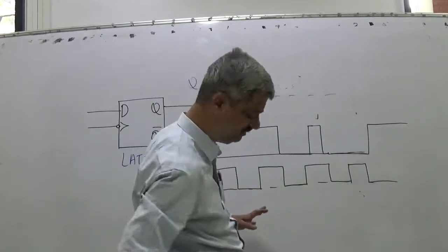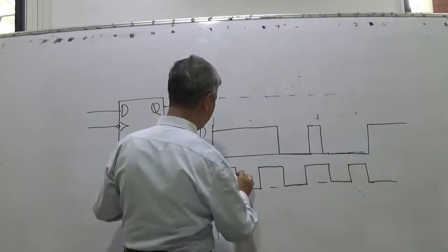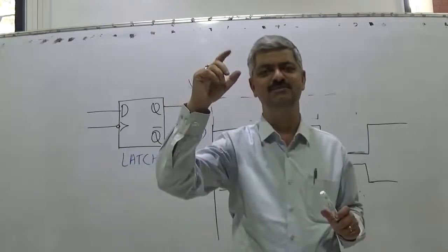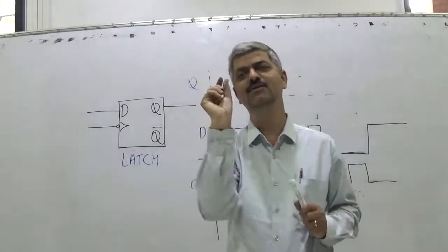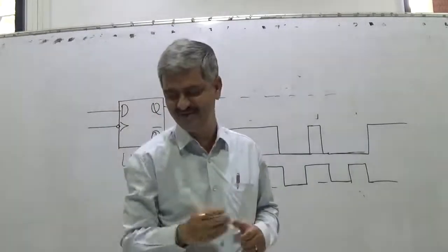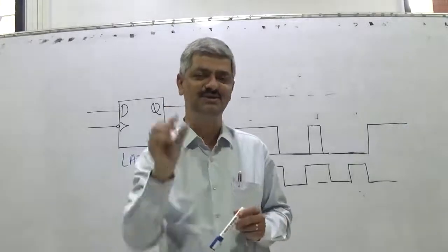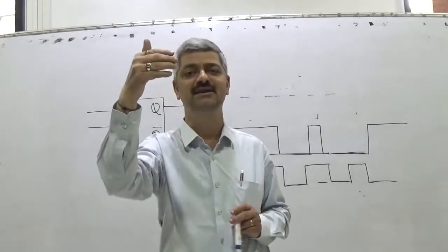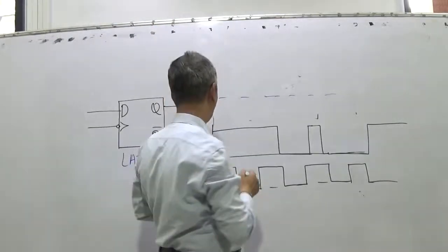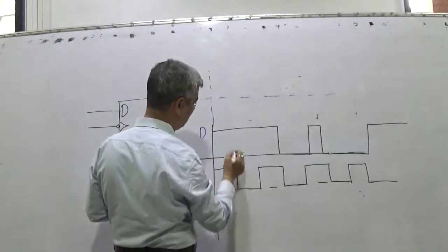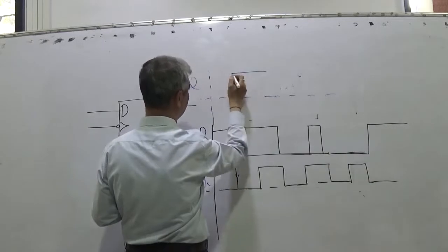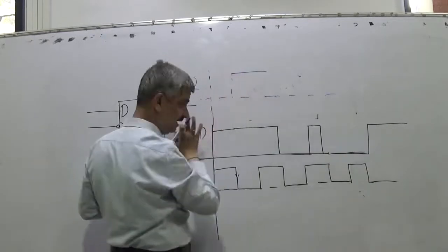Logic is very simple. At the time of falling edge, it is just as if a shutter opens. In a photograph, what is seen? Now the concept of shutter and all that is history. You are having a snapshot. When the shutter opens, only the things beyond the lens of the camera are recorded inside the camera. So whatever is the value at this falling edge, what is D? This one. So D becomes 1. Previously it may be 1, it may be 0. It's immaterial. We can't say.